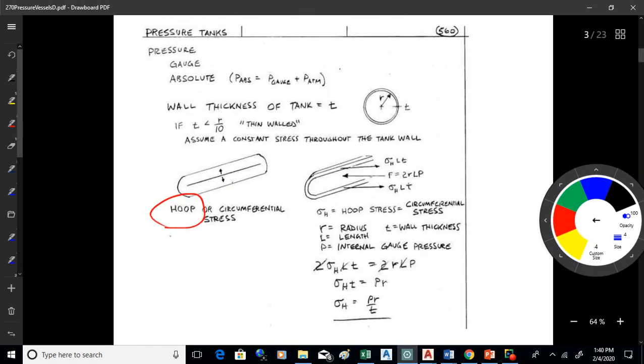So I have that sketched up there down below on the right. Now, what we have here for the pressure is a rectangular area that looks like that. This dimension will be 2 times the radius, and then however long we're looking at will be L. So we have a rectangular area of 2r times L. You multiply that area by the internal pressure.